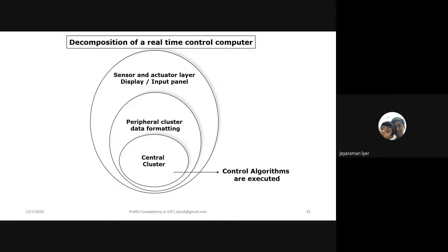I have a problem. Look at it. I want to make an automatic door closure. This is a simple thing. This automatic door closure, the door is a mechanical device with a lot of sluggishness, a lot of inertia. So nothing will work in 1 nanosecond, 1 picosecond, 1 microsecond. It will work in a few milliseconds. You take a contactor or a relay or something like that. A relay closes in 5 milliseconds or 2 milliseconds. A contactor closes in 200 milliseconds. Suppose I am giving an input to the relay. The relay's NC to NO or NO to NC change will happen after 200 milliseconds.